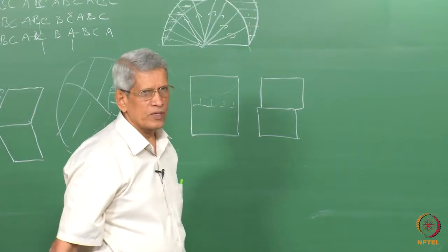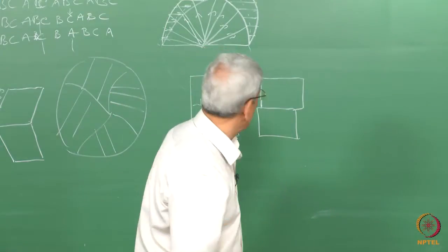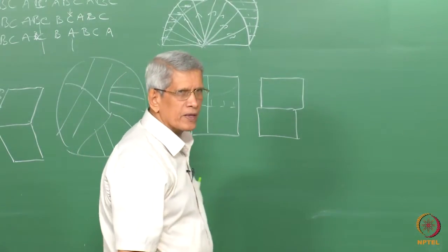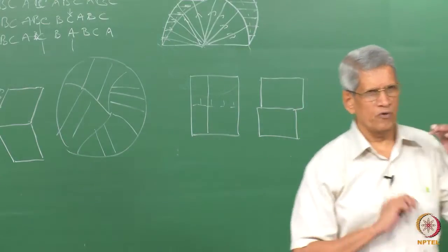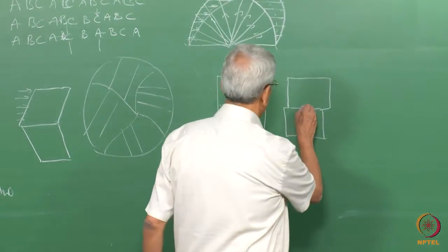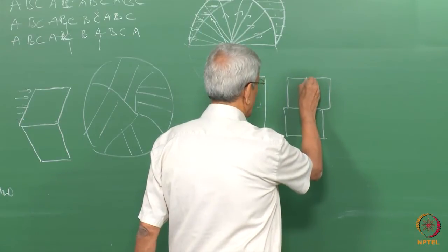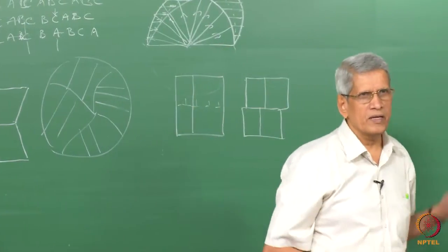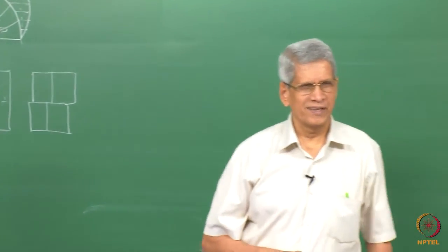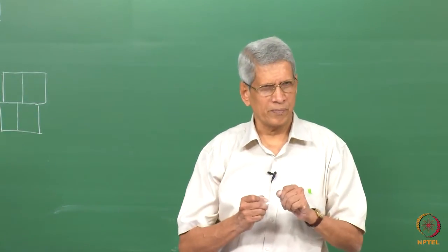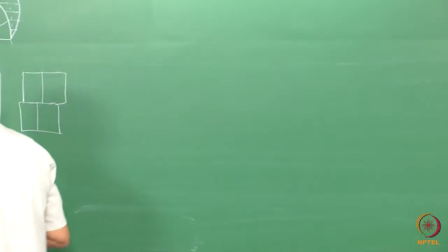How can this be verified, whether it is occurring or not? Suppose on a polished sample I draw a line before I deform the sample. Then, if it has deformed by slip taking place along this line, what will happen? This line will be shifted by this much, and the lines will occur with a gap. That means the deformation is discontinuous. If the deformation were continuous, they would have tilted and stayed joined together. That does not occur. This is one way.